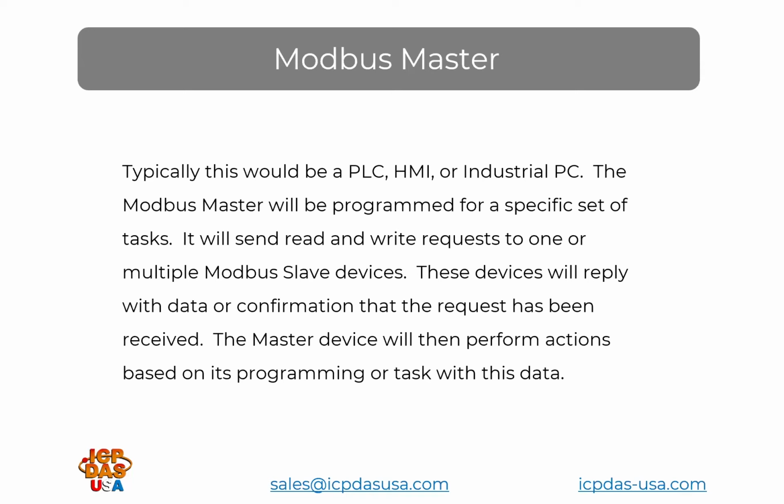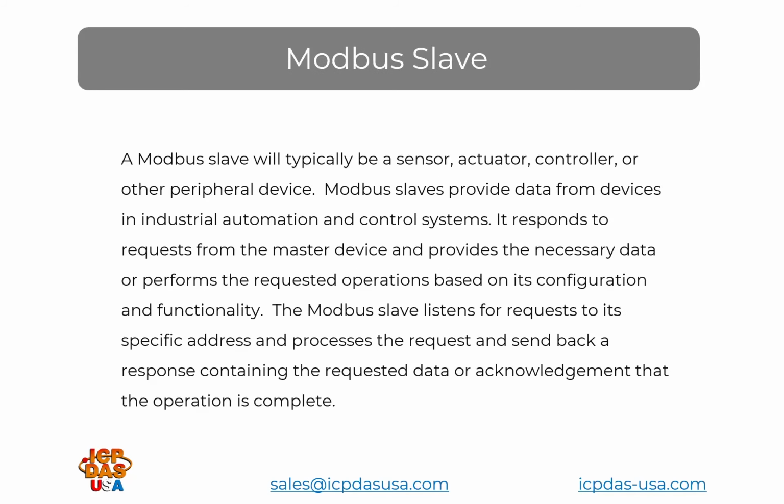Let's say the PLC was tasked with monitoring a set of cold storage rooms. Each room will have a desired temperature and humidity requirement based on what is stored in that particular room. The PLC will monitor the temperature and humidity of the rooms with sensors and control the refrigeration to maintain the environment. It would also be able to monitor if the doors were left open or if the room were empty. Under these circumstances, it could either sound an alarm or adjust the temperature to save electricity.